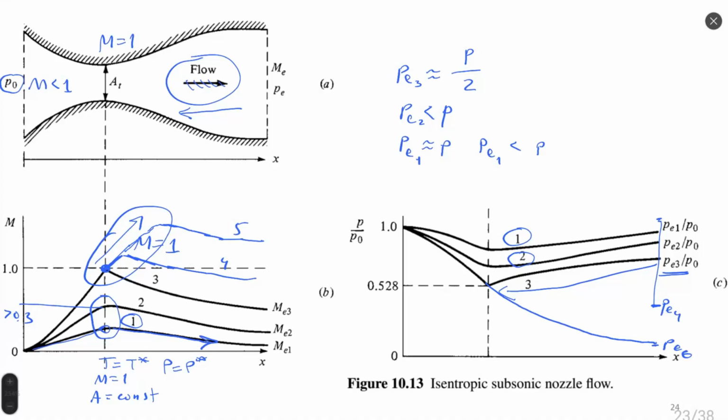throat. Once we combine these parameters and elaborate just one parameter which describes this process, we can use a definition of quantity of gas flowing through the nozzle, which is mass flow rate: m dot is equal to area multiplied by density and multiplied by velocity.